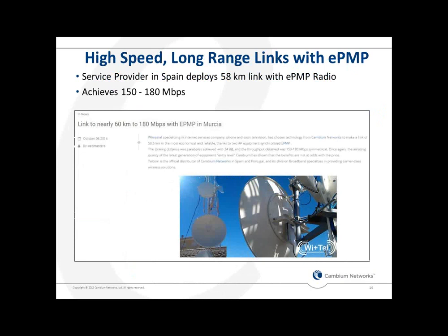We have a lot of people out there using the ePMP in point-to-point mode. Here's a very interesting case. Recently we had a service provider in Spain who deployed what I think might be the longest ePMP link out there. They used a very large dish. This is not a forced dish. This is probably a 3-foot dish here. It's a 34 dBi dish, and they were able to achieve 58 kilometers with their ePMP radio and 150 to 180 megabits per second of throughput.